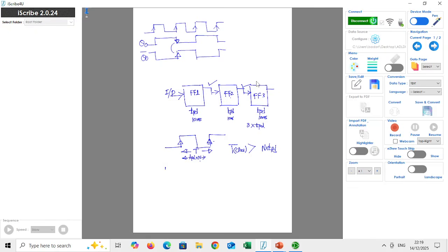So there is a formula which calculates the highest frequency possible with an asynchronous counter. It's equivalent to 1 divided by the period, 1 divided by the total delay of the counter, which is nothing but TPD into N. This is the formula for calculating the highest frequency. For any frequencies higher than this, the outputs are not reliable. So generally it's recommended that the operating frequency should be less than this value, even though it is an indicative highest frequency.